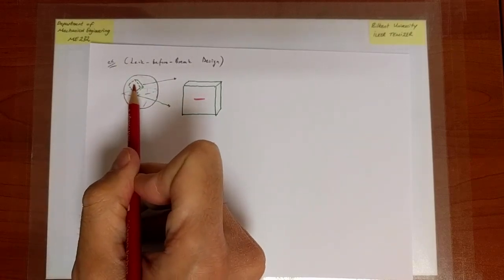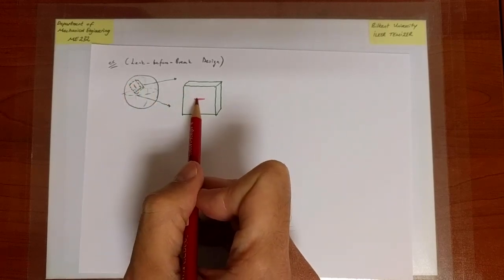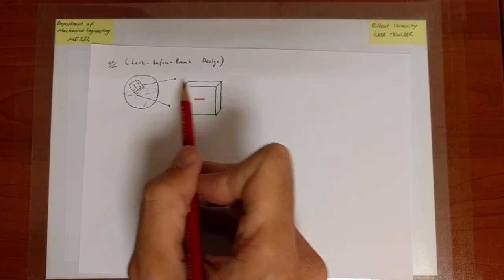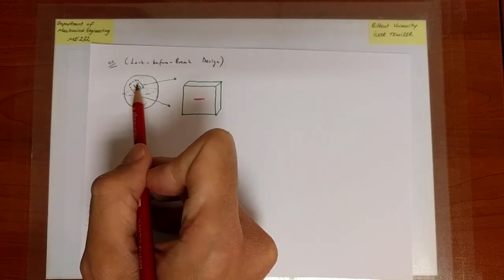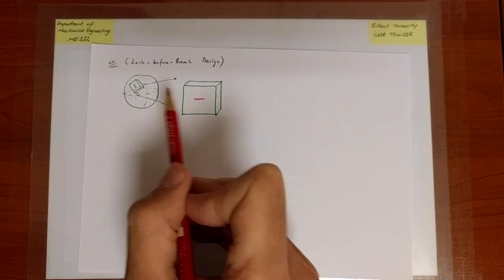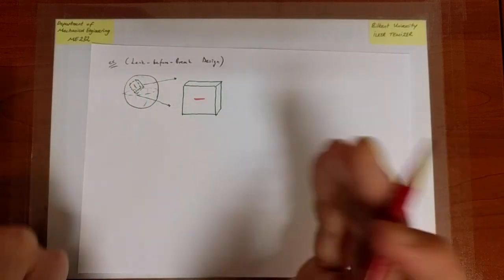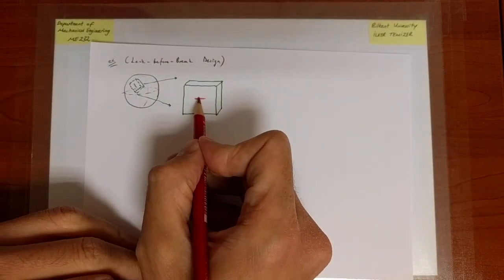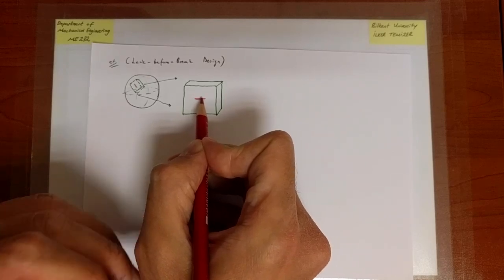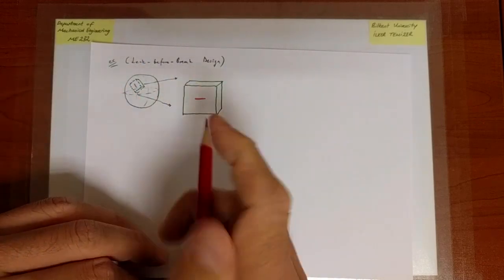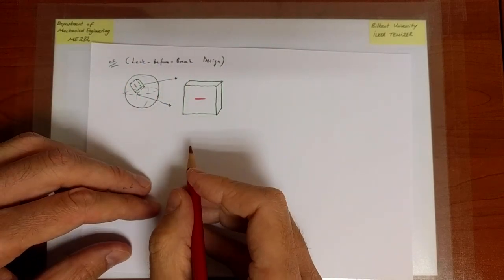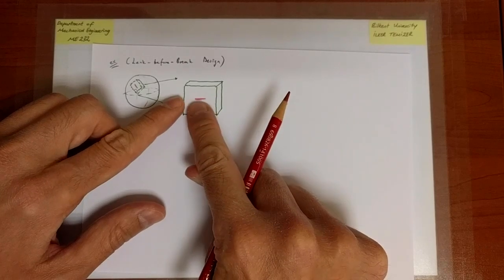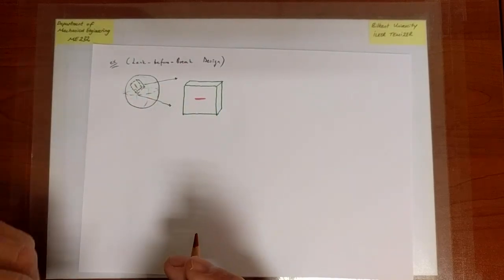Eventually, what I'm going to assume is that that crack is very small. With respect to the size of the crack, this block will be larger, but still, with respect to the size of the sphere, this green block will be small. So this is an exaggeration. Imagine the Earth looks flat with respect to us, because our dimensions are very small with respect to the size of the Earth. So if the size of the crack is sufficiently small, the surrounding material will look almost flat. So I'm going to idealize the surrounding material to be almost flat. And the width that I am considering here, I'm going to assume is sufficiently large with respect to the size of the crack. We'll come back to that in a second.